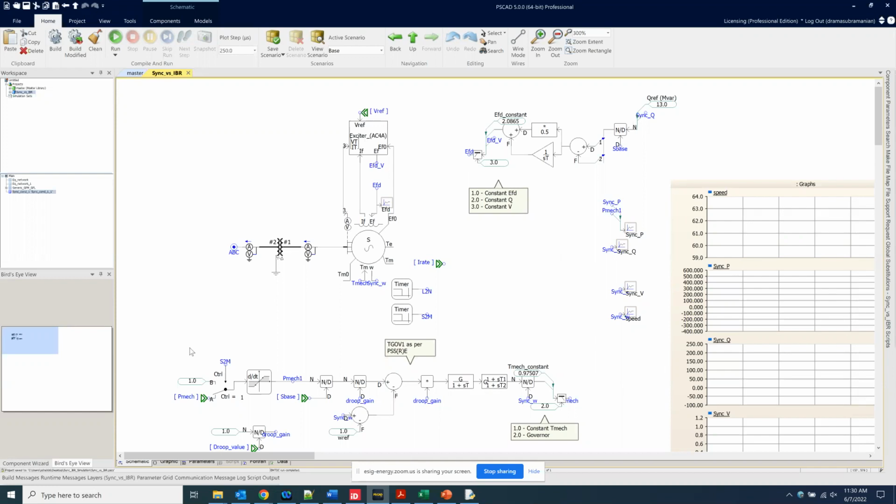A lot of static excitation schemes will look at the terminal voltage, rectify it, and then feed the DC exciter. Those machines cannot self-start unless there's some residual flux in the core of the machine. But let's say we remove that static excitation and we put constant field excitation. So whatever happens on the terminal side, we will not change the DC excitation voltage.